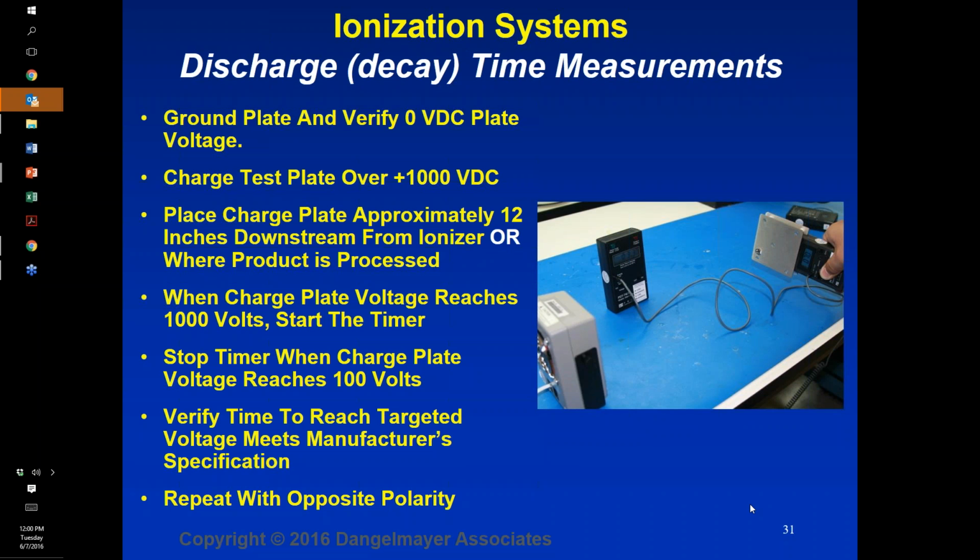There are many things that affect the voltage on an object when it's in an ionized environment. The ionizers that are typically used in electronics applications today are typically balanced to better than plus or minus 20 volts, so we're really not very concerned that the ionizer is going to create issues for isolated objects. Quite frankly, we have some arguments with this 35 volt specification because it doesn't take into consideration the capacitance or the size of the object that it's talking about.